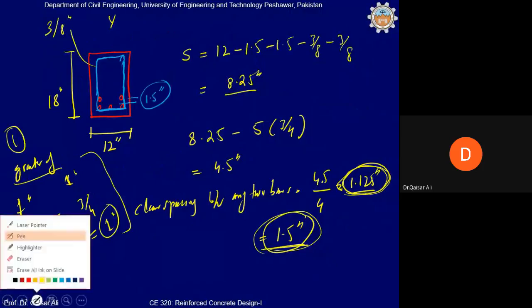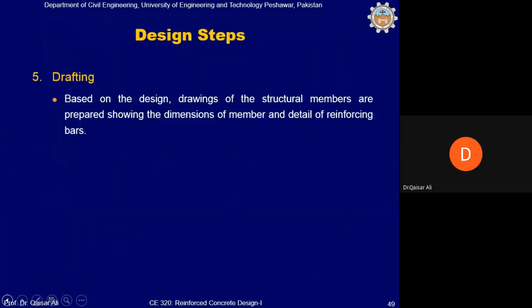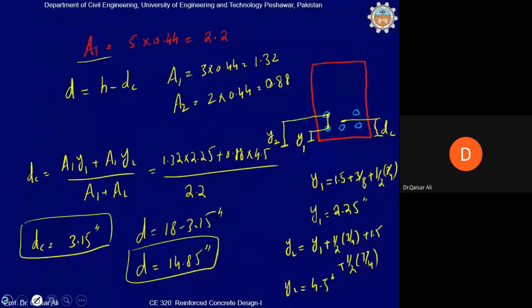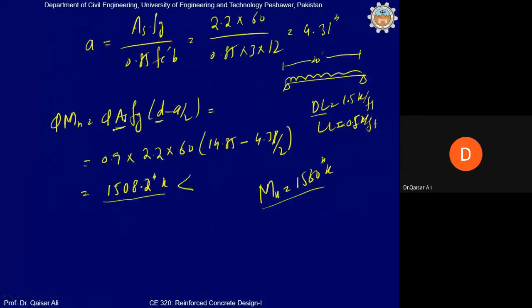So it will increase the reinforcement, and if you look at the flexure capacity equation, you can increase the flexure capacity by increasing the area or effective depth or by increasing the grade of steel. However, since normally the material properties are fixed, you can increase the capacity by increasing the area or by increasing the depth of the beam.